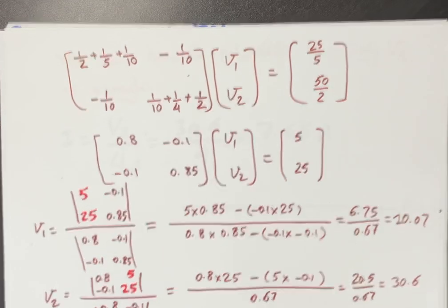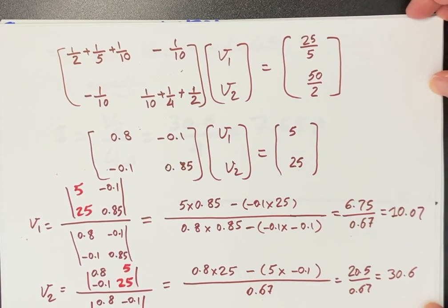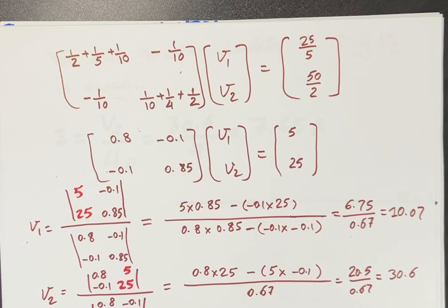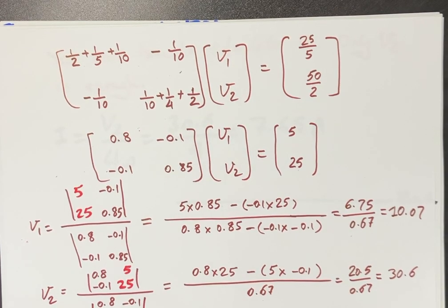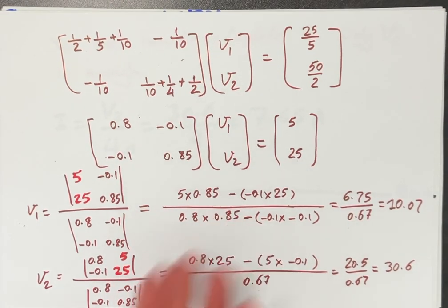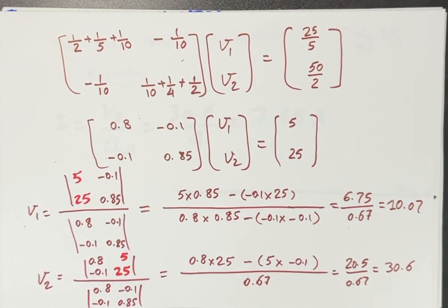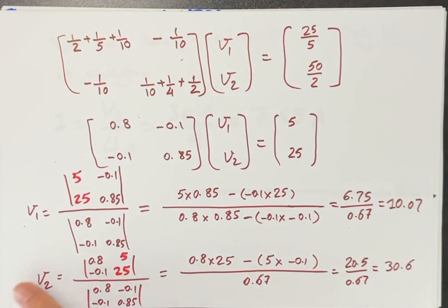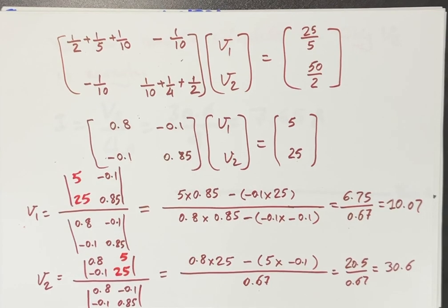Then obviously we need to solve this. The first step, we can convert them to decimals to better calculate the determinants. When you use determinants, you don't have to obtain both variables v1 and v2. You only need v2 because in the question we are asked to calculate the current flowing through a 4 ohm resistance.